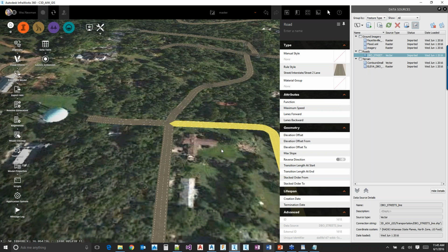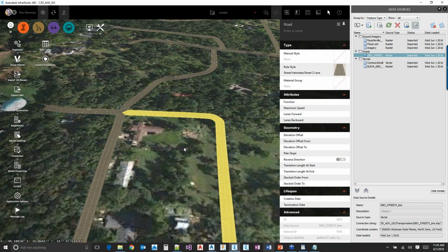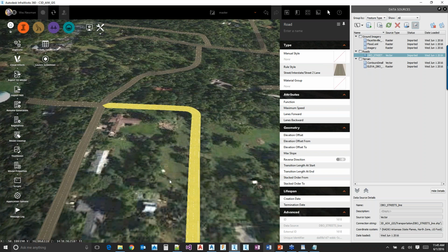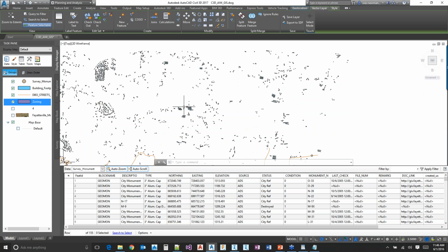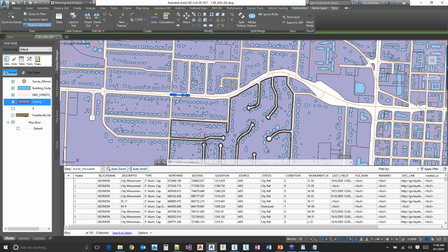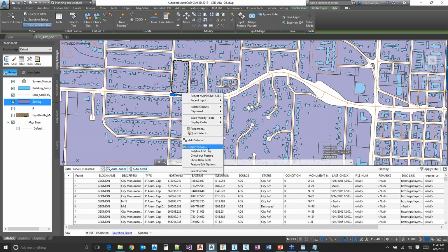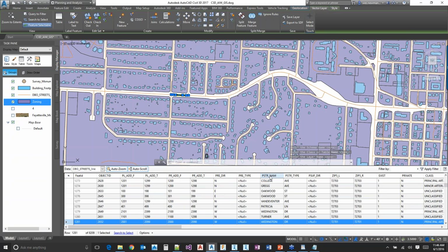And so this is where we may want to start leveraging some of the GIS data to maybe give it a name and pull that information from the GIS file. This is where you may want to utilize InfraWorks, Civil 3D to look at the data. So if I pull back out and go grab one of these roads here, show that, now we can see the actual name.